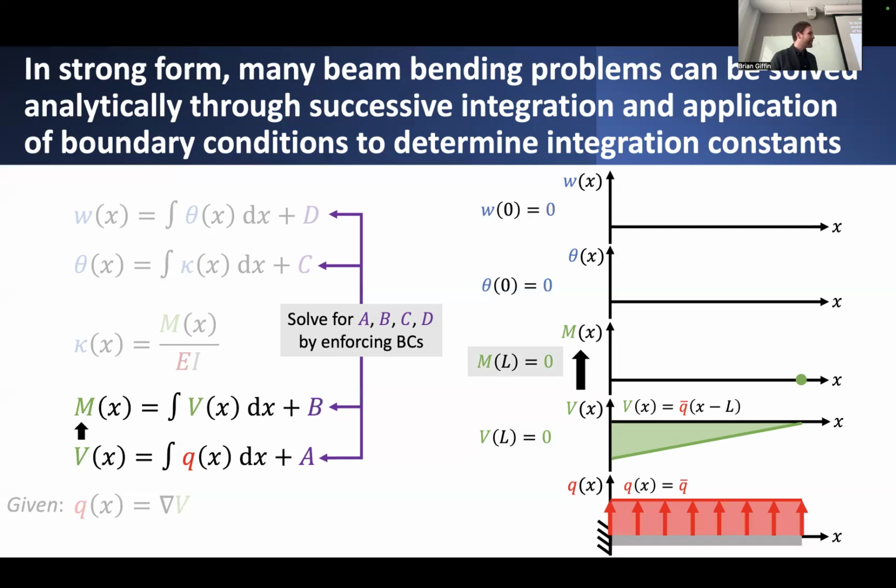And also, it's important to note that at least for this boundary value problem that I've constructed, I've also specified the end shear force at one of the ends of the beam. So actually at the right-hand end of the beam, I've specified that the shear force there has to be equal to 0. I'm technically not applying any kind of end load there, but knowing that is crucial information.